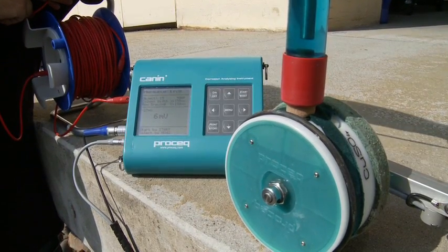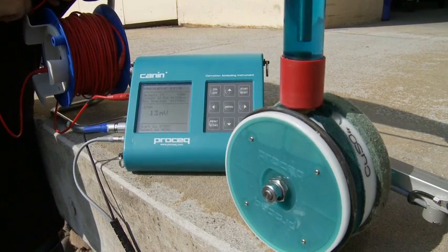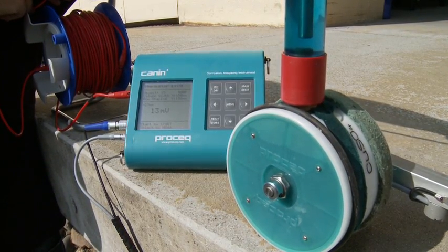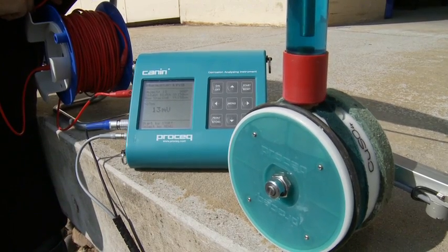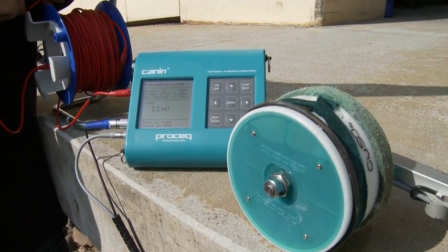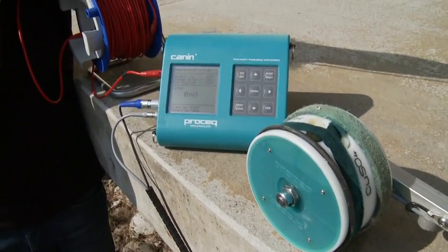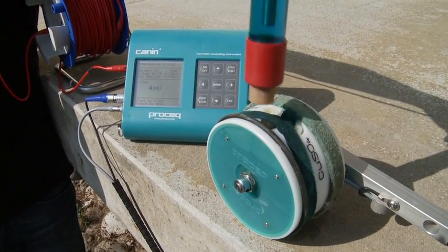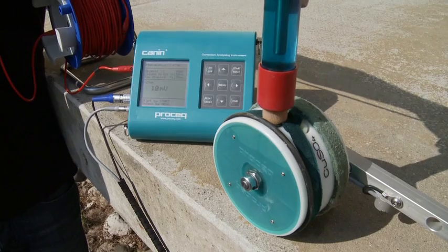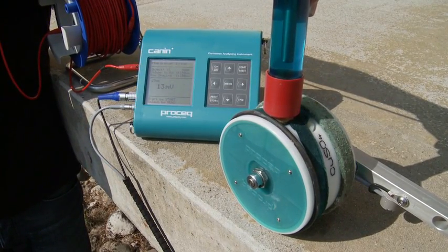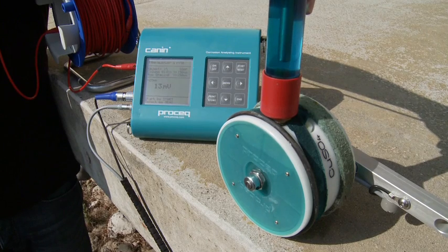A further check is to use a reference electrode. In this case, the rod electrode is used as a reference electrode and the potential of the two electrodes cancel each other out. For correct operation, the tolerance values of ±5 millivolts for the rod electrode and ±20 millivolts for the wheel electrode are acceptable. If the electrodes are out of tolerance, clean them.